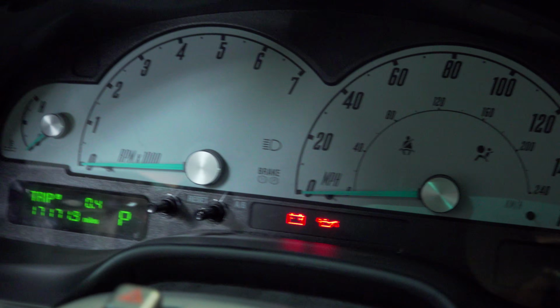So this rules out all those splices that we were looking at, and the connectors, and just about everything up to that auxiliary connector that we saw in the diagrams. We will have to get to the front electronics module and be 100% and apply power there and see if everything lights up. That will rule out absolutely everything downstream of the front electronics module. And if that's the case, well, we have an internal issue with the front electronics module.